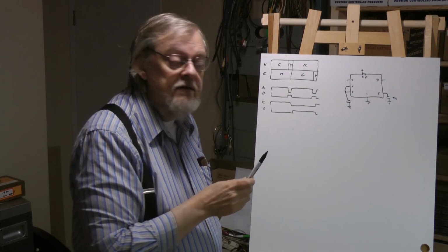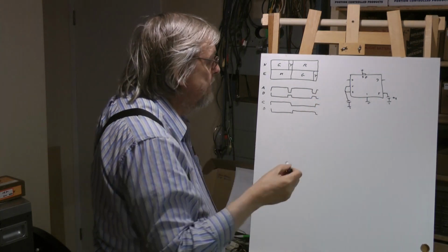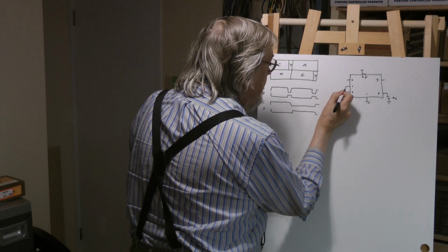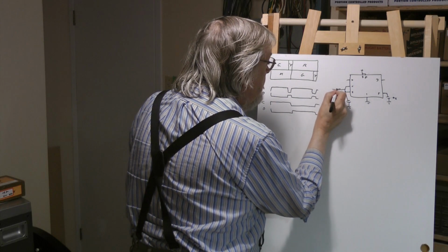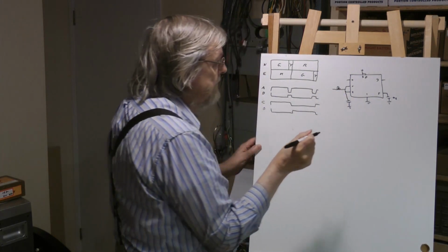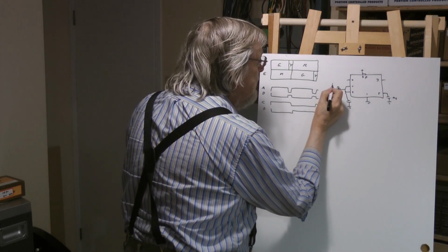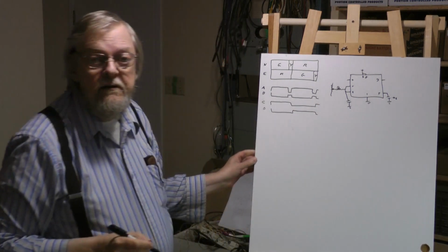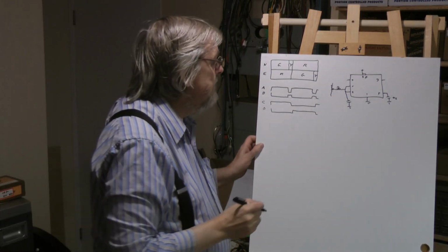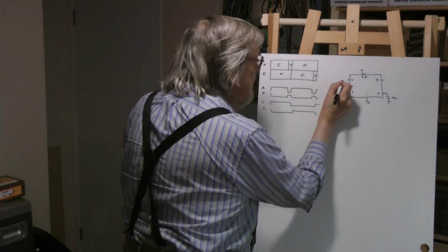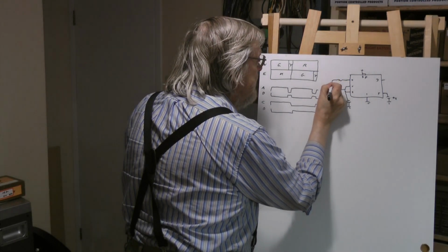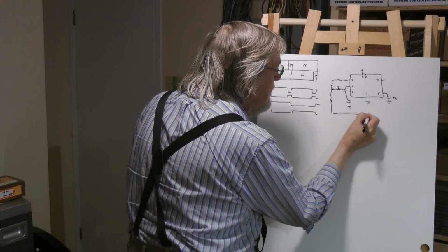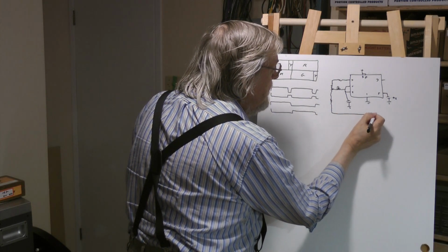Normally they use a resistor up here for charging, but I'm not going to do that because I want more control. I'm going to put a pot here so we can adjust our overall time, and a pot here so we can adjust our duty cycle for our green-red time, our green-yellow time, which would go in there, and another resistor that I'm going to charge over here.